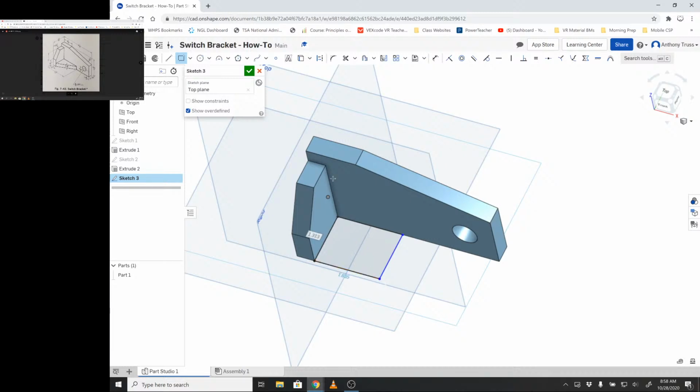At this point, I'm going to press D for my dimension tool, and click this point that includes the 7/16, so we shouldn't even have to subtract, and then this point. At that location, we should be able to do 2.5, which brings out that measurement to exactly where it needs to go. I don't even need to worry about the depth measurement. I have the two points that I need to establish a diagonal, and that would be with your line tool, press L. You want to snap to these two points.